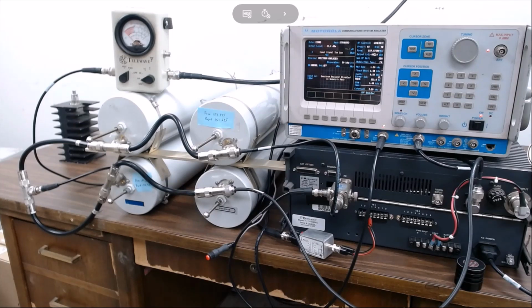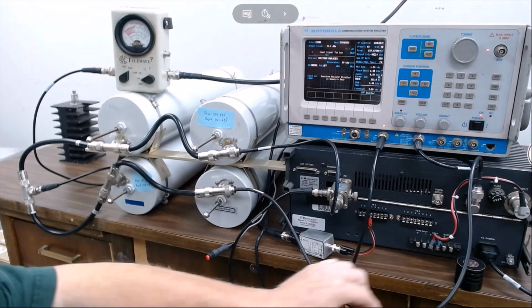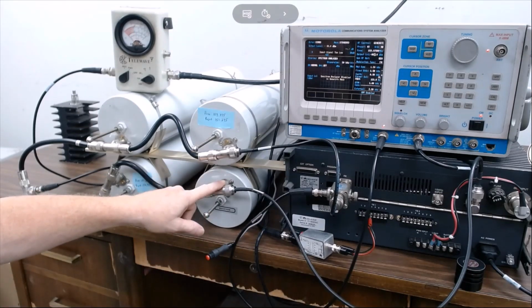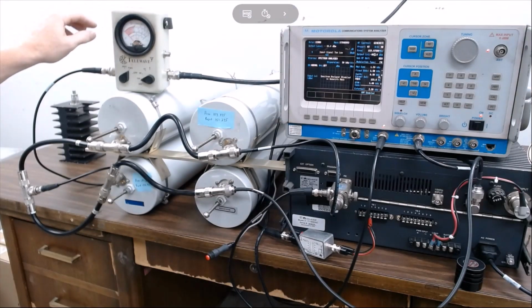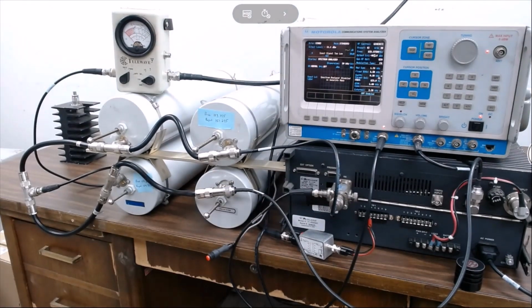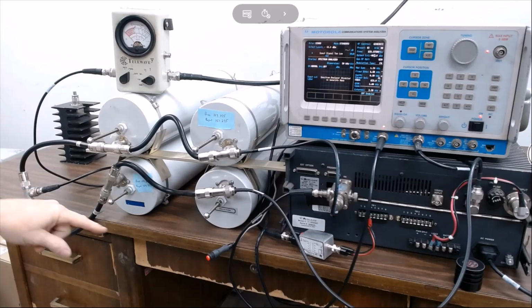Okay, for our final two tests here, we've now hooked the transmitter up to the duplexer, and we've inserted a watt meter in line with our antenna output here, and we're going to do the 12 dB SINAD again for coming in here on our ISO-T, and then we're just going to key our transmitter and confirm that we have no internal interference, and also if there was something out there that was causing a mix and sending a signal back in on our receiver as power went out into the antenna, we would see it doing this test.